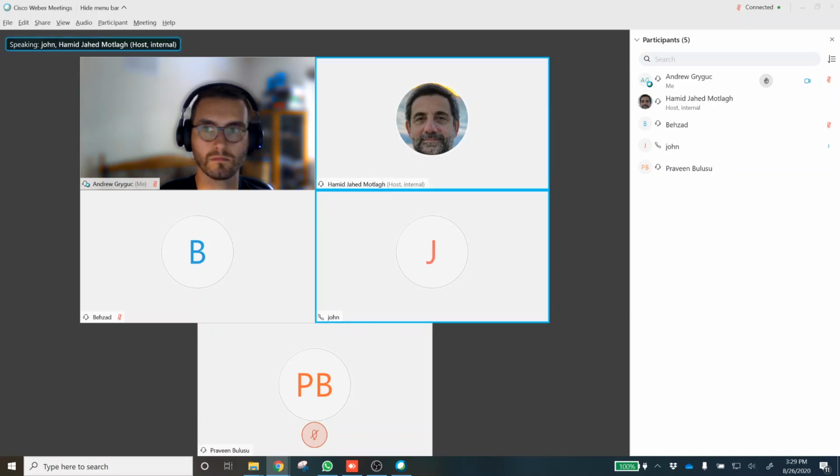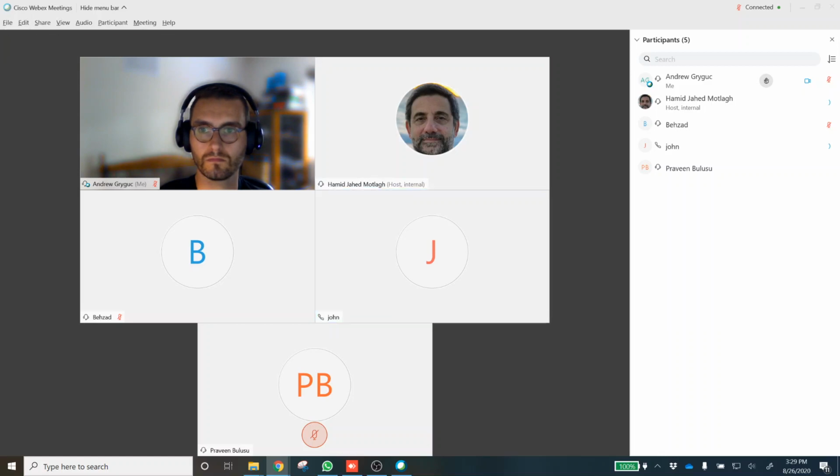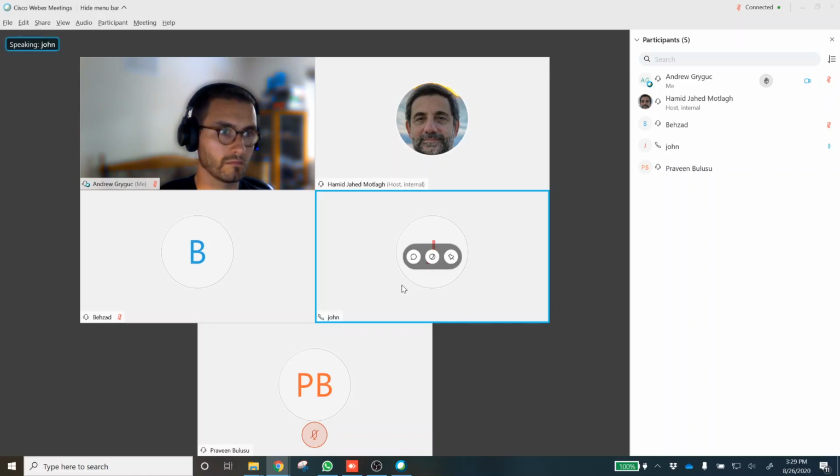What is the strength? We have many components in these suspension systems that are case hardened, so we don't have a feel for what this case hardening does, especially in a strength scenario. So which material properties should we use in our finite element model? Should we go with the case hardened material properties, or should we go with the base material properties, especially for strength simulations, not the fatigue, but the strength?